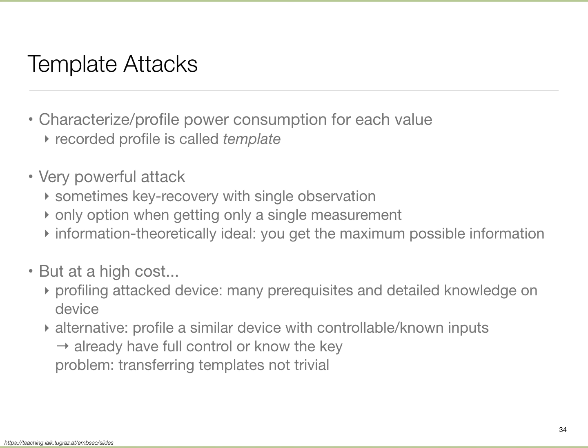So firstly, at a very high level, things started out with what is called simple power analysis, which is the equivalent of looking at the trace, and like I was showing, you can identify loops and things like that. When you are doing these kinds of things, a very common approach is something like template matching. I will have a template when it does one operation, a different template when it's doing another operation, and then I'm going to do template matching.